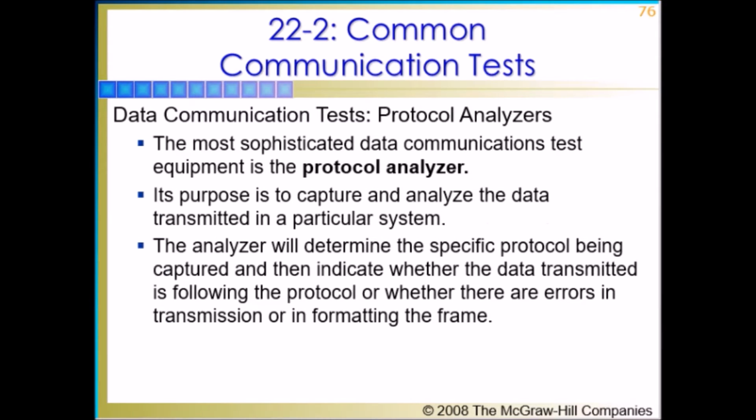Protocol analyzers. The most sophisticated data communication test equipment is a protocol analyzer. Its purpose is to capture and analyze the data transmitted in a particular system. Most data communication systems transmit data in frames or packets that include preamble information such as sync bits or frames, start of header codes, addresses of source and destination, and a finite block of data, followed by the error detection code.